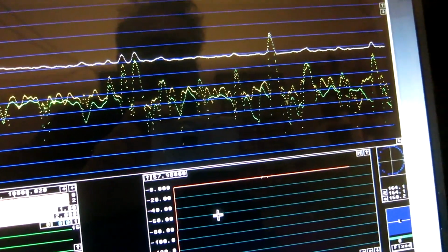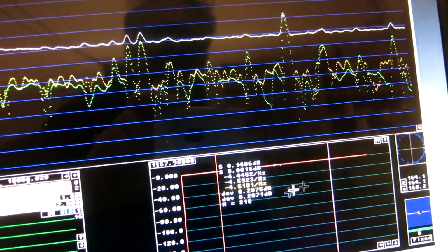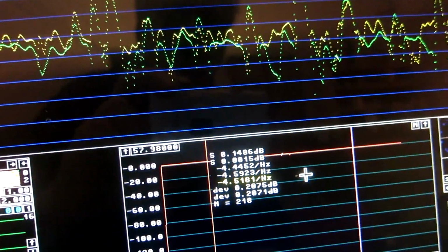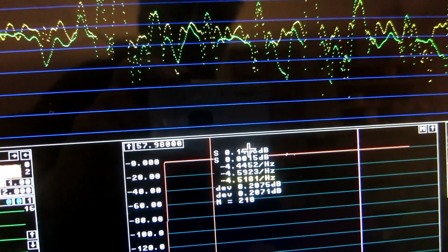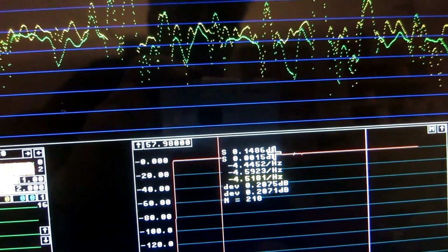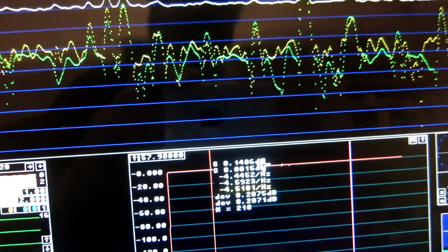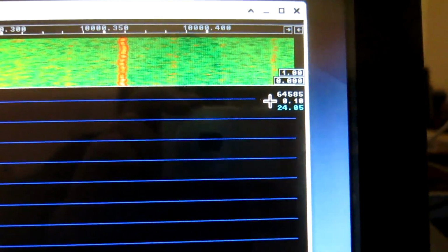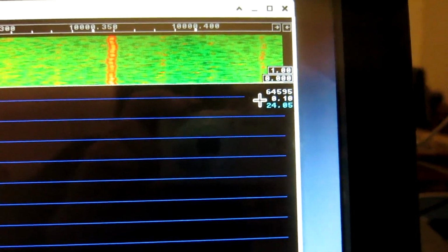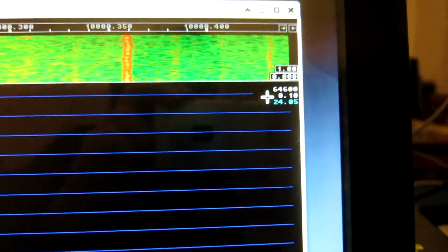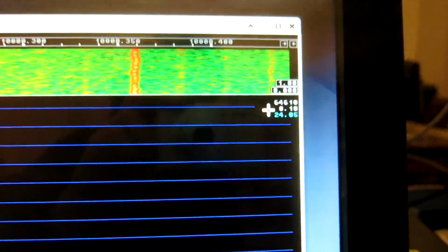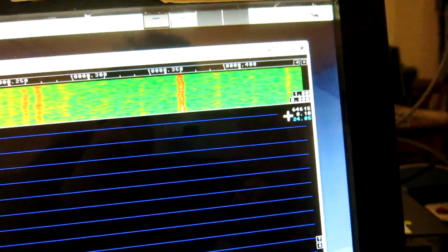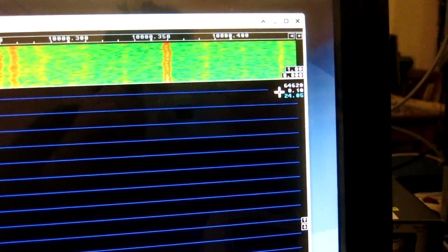I'm checking the carrier and I want to read it out to make sure that it has not changed too much. It has increased by nearly 0.1 dB, and I can understand that by looking here also. The average power spectrum is 0.1 dB above the correlation spectrum average. But this is just 0.1 dB and I neglect that.